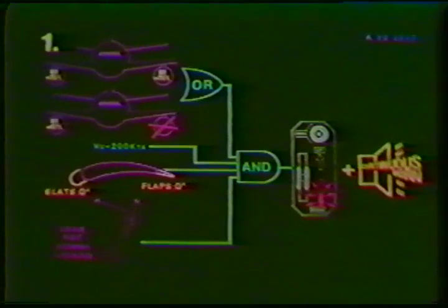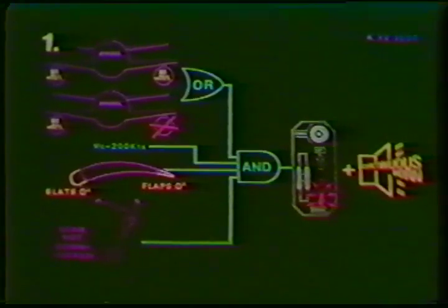As we know from previous aircraft models, a gear warning horn will sound whenever the gear is unsafe to land with certain conditions existing. On the A300, a continuous horn will sound and be accompanied by an illuminated down red arrow under 3 different conditions.